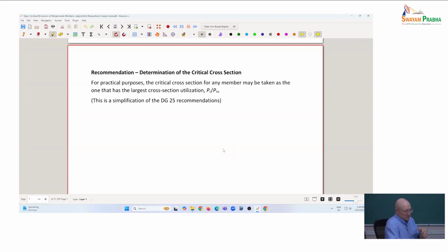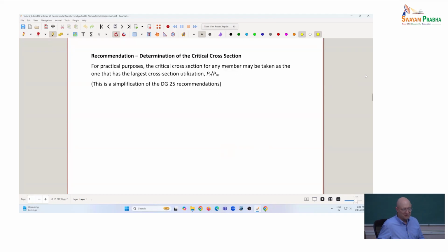You can do that based on FY for getting your effective area. That's going to be the one in AISC that tends to be the critical section. This is where Eurocode or the Indian code, the way you have your column strength equations, actually works much better here. It's going to be that section, definitely, in your case.